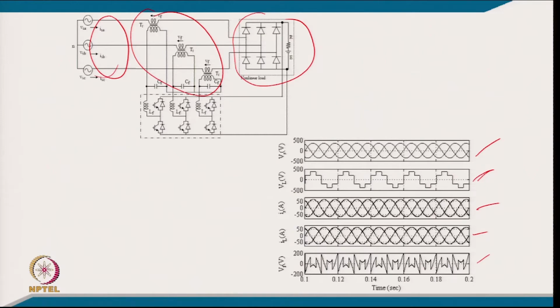through diode and charge the battery. This also gives a very interesting result in the sense that you do not have any ripple voltage on the DC link, as far as the diode rectifier is concerned, because we will be charging from 3 sinusoidal currents, and the sum of the 3 currents at any moment of time is 0. So, that is about the simulated waveform.